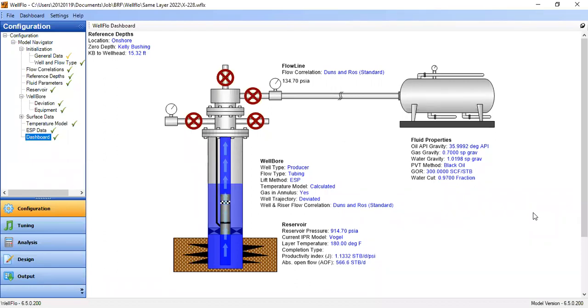So today we will use WellFlo, and the case is again about workover. In this workover, I'm planning to perform perforation addition. Okay, I will just add perforation at the same reservoir. So I will expect that the skin due to limited entry or skin due to partial penetration will be reduced because I add perforation interval, and because the skin will be reduced, I expect the productivity index to be improved.